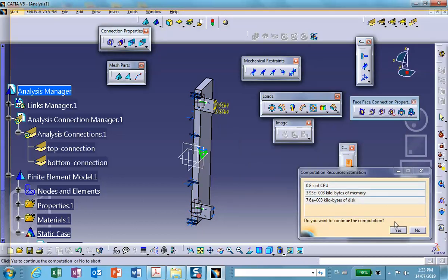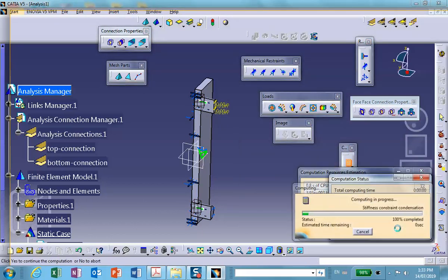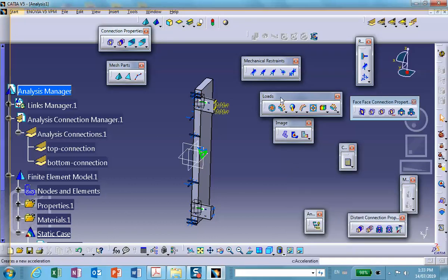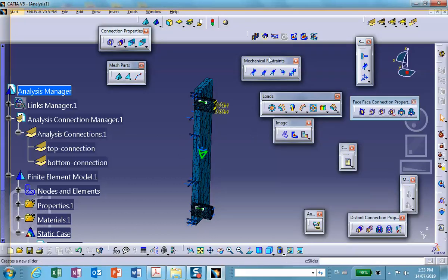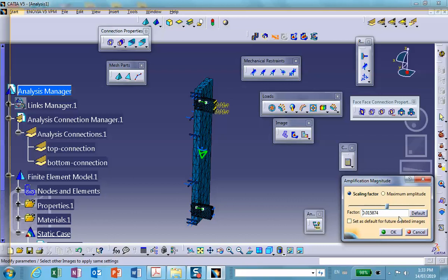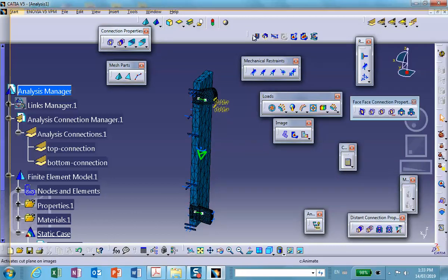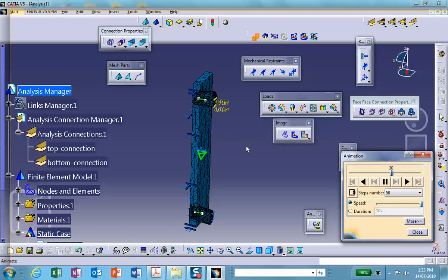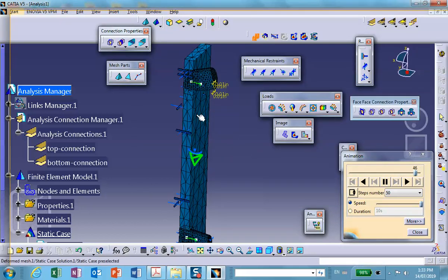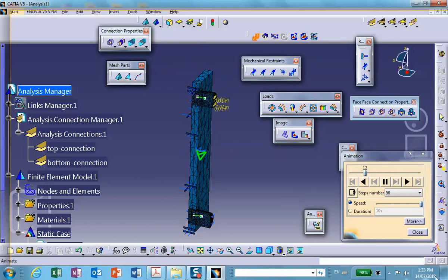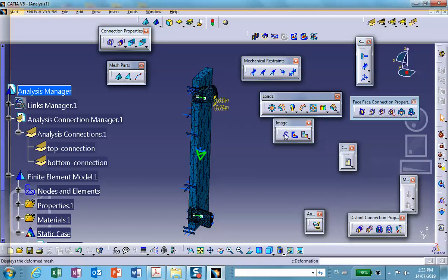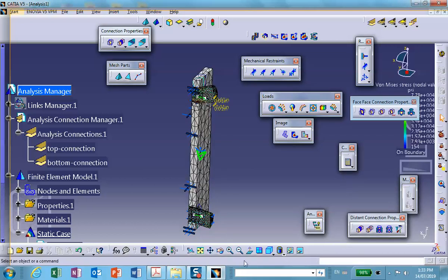Don't worry about the warning. Run it, and you can see that it's going to look good. Now, I'm not discussing the quality of the numbers, but it's running. It did run, no problem. This is exactly the way it should be. Except that in the previous run, without any symmetry, I made the elements around the hole much finer, so probably they're more reliable. And you can look at the stress distribution.